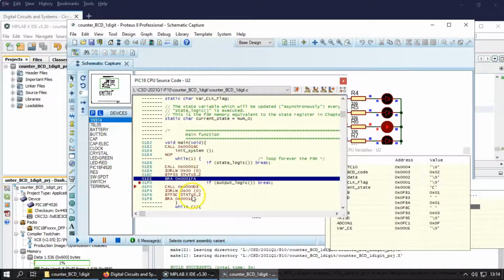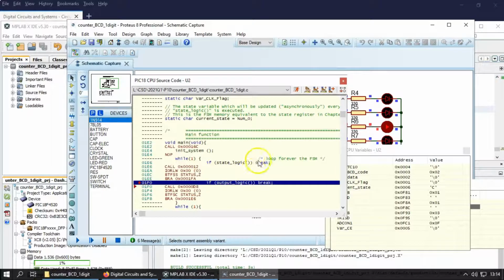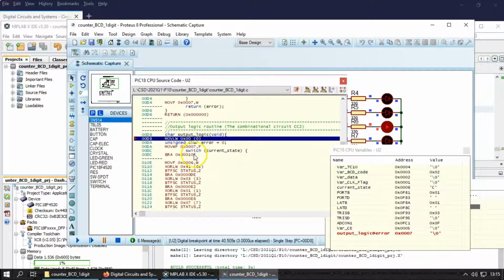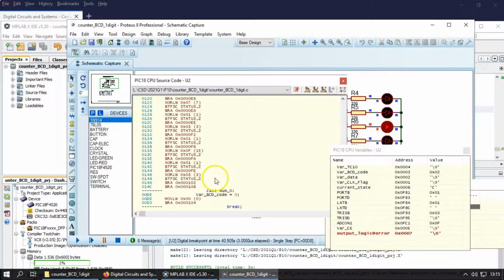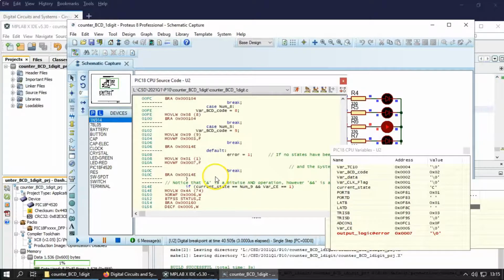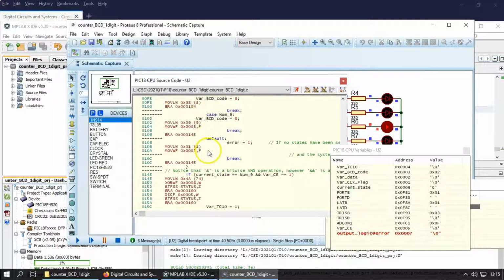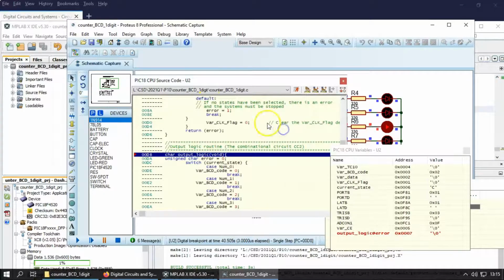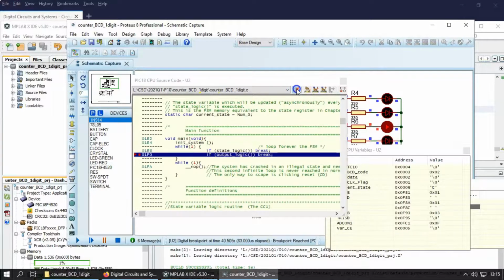So you have several instructions here, and then you have several more instructions inside the if. You see, if you are moving around the if, you have a lot of instructions to write and to do every idea that you've got here defined in C. Okay, so in the end, if you go from one breakpoint to the next, it takes 83 microseconds.